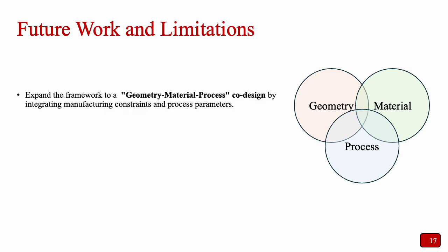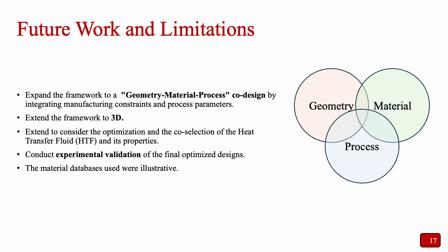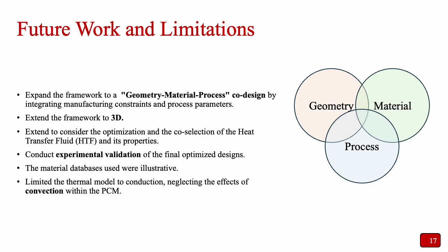We plan to expand the framework to a geometry-material-process co-design by integrating manufacturing constraints and process parameters. We are also extending the framework to 3D, then adding the co-selection of the heat transfer fluid and moving towards experimental validation of the optimized designs. We also acknowledge the current limitations. The material databases used were illustrative and the thermal model was limited to conduction, neglecting the effects of convection, which will be an important focus of future research.